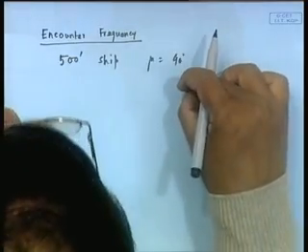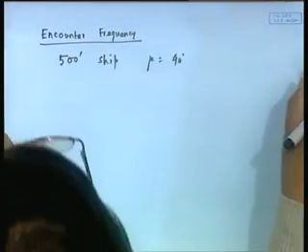Let me emphasize this part of heading angle. In some reference books, you will find heading angle is defined between the minus x axis, that is the opposite of the wave direction, and the ship, so that 0 degree becomes head waves. Some books use that. We are using a consistent system where the direction of V ship and the direction of V wave, the angle between them is mu. That is why for us 180 degree is this.